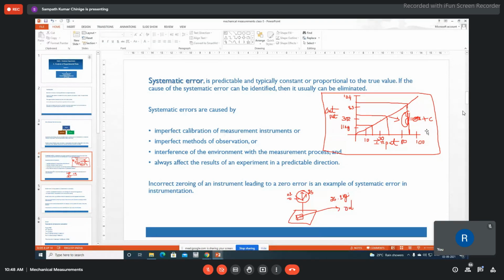So to maintain this bridge circuit properly, you will vary the current accordingly. Whatever reduction in the resistance, you will put more or less current. So the deviation in the current is proportional to the flow. Therefore, you are linking those two and you are able to measure the flow or velocity of the flow. So this is the principle.